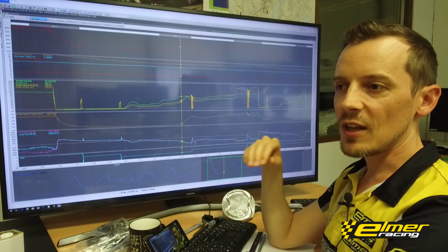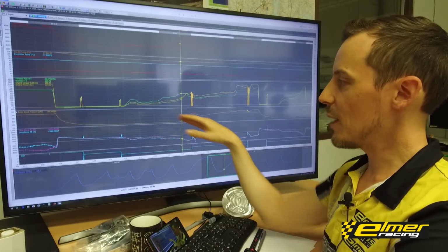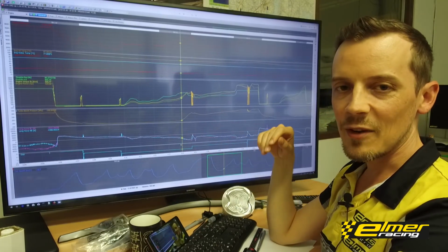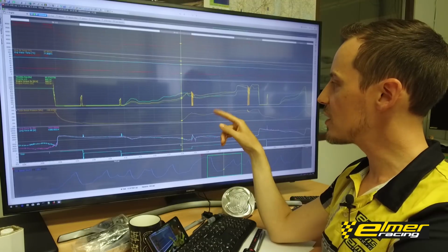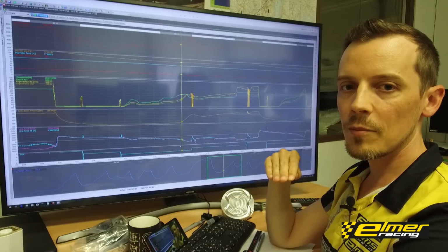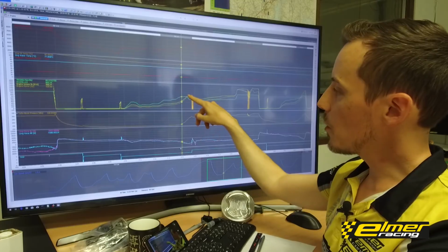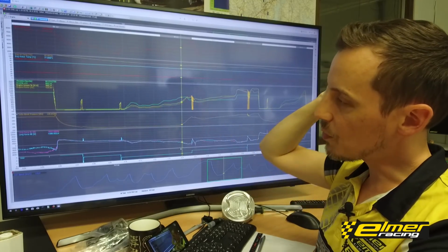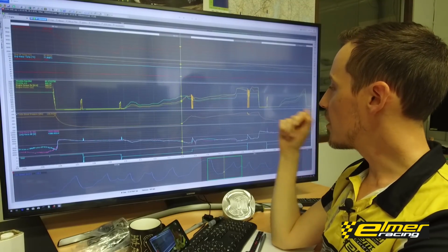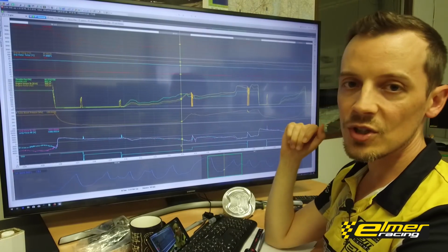With an actual ECU you can of course get a much better throttle response than what is shown here. It's not necessarily immediately visible from these curves, but it has a very poor throttle response, but this can of course be improved with the pedal to power mapping on the ECU. And so before we reach boost, we're not even at 100% power request from what the engine is capable of producing, so that seemed very good. And looking of course through the rest of the lap also, the situation is pretty much the same.